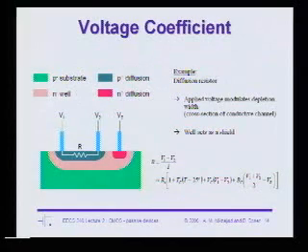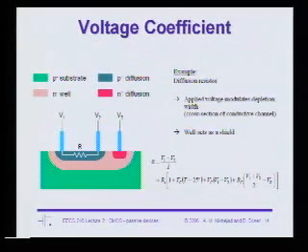Okay. So coming to your question. As we've discussed already, all these resistors that are physically in the substrate are basically junctions, right? And the depletion region width is a function of the reverse bias, which changes the thickness of the material, so you end up getting a voltage coefficient. This is one way to describe the variation in resistance. You can see that it's a linearized model, right? Clearly this is a simplification, but for small changes it should be pretty good. It's just like doing a Taylor series expansion.